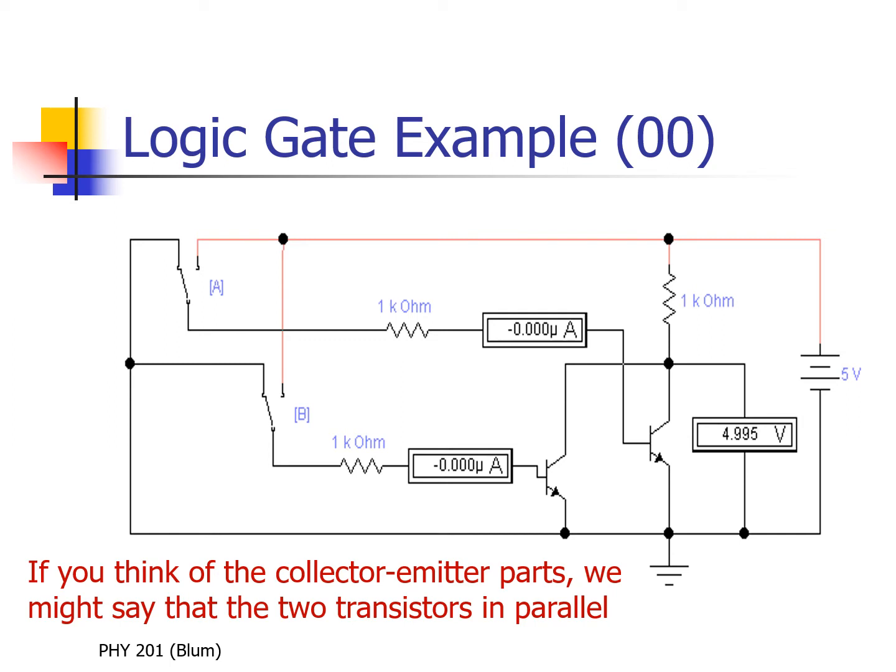And then I have that one single 1 kilo ohm resistor above it. So most of the 5 volts is dropped across these high resistances. So I put in two lows and got a high voltage. That's one of my 4 states.